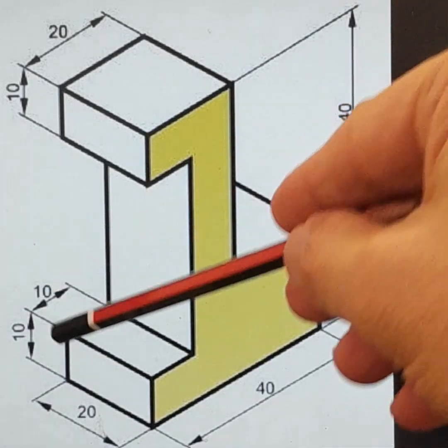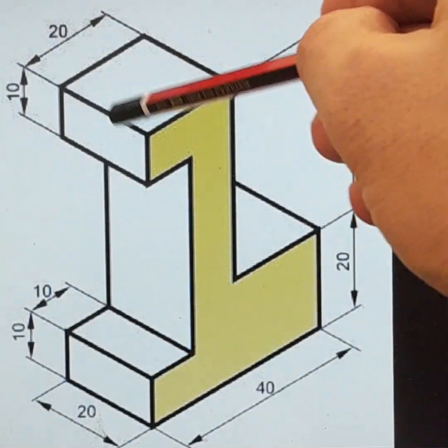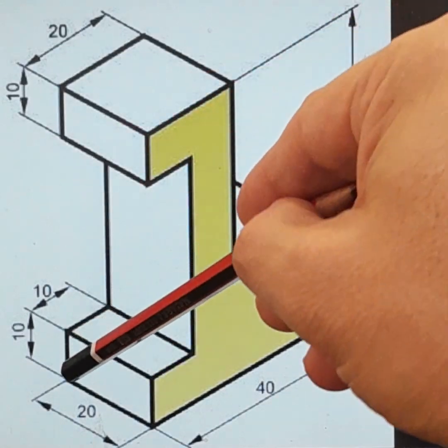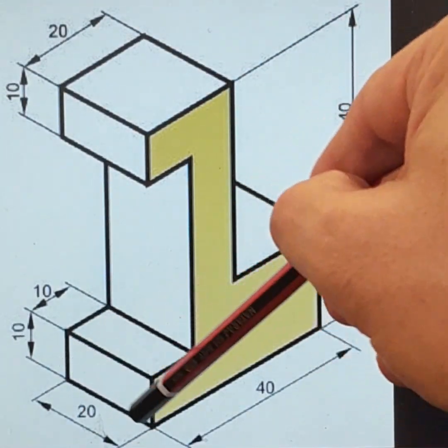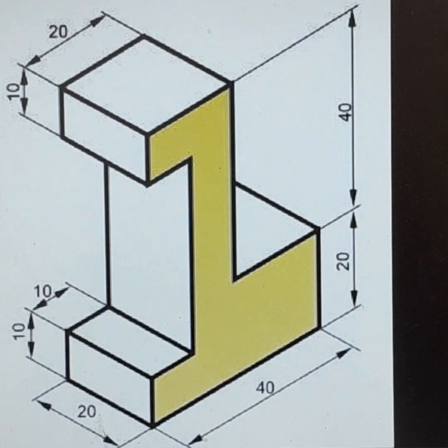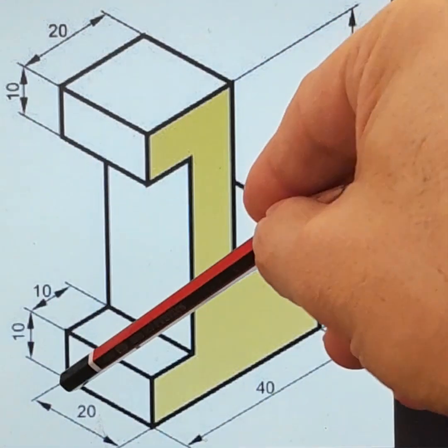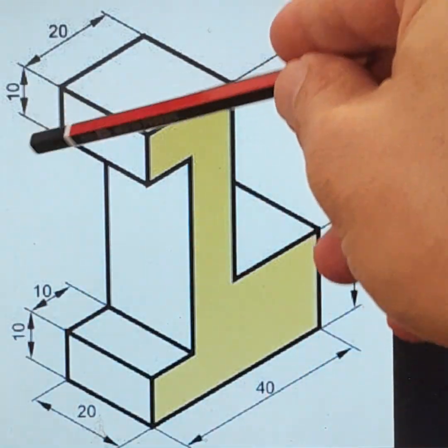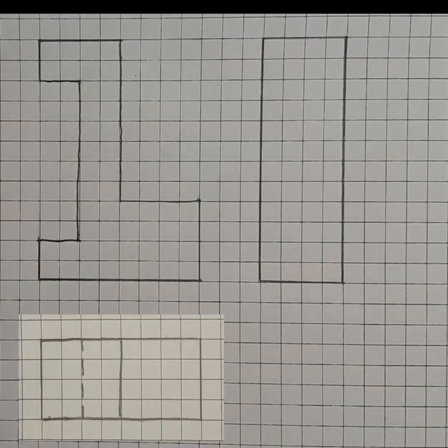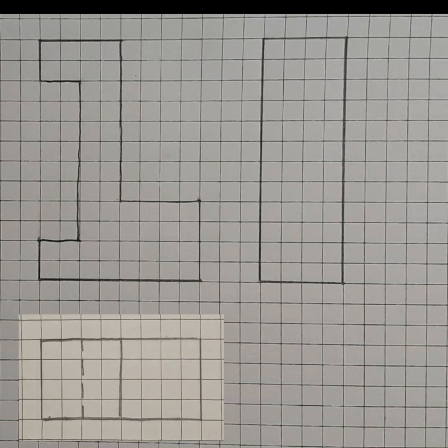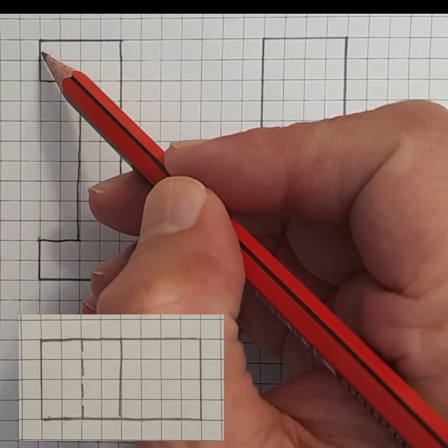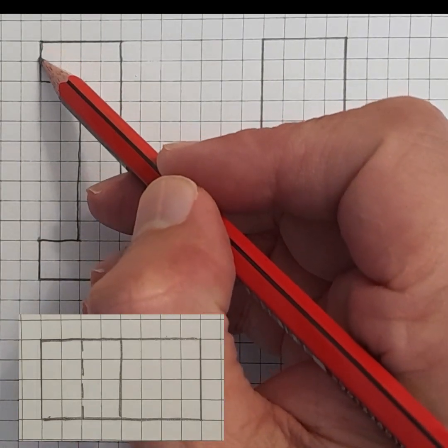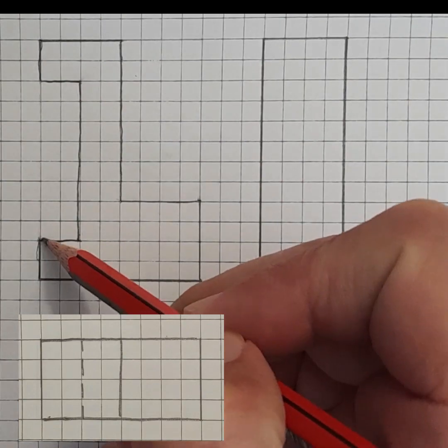In the drawing, these are the two small rectangles at the top and at the bottom. Length is 20 millimeter, which is the width of the part, and width, which is this height, is 10 millimeter. Actually, this dimension we can get from the views that we have drawn. These two rectangles, the above and the bottom one, are represented here by these two lines.